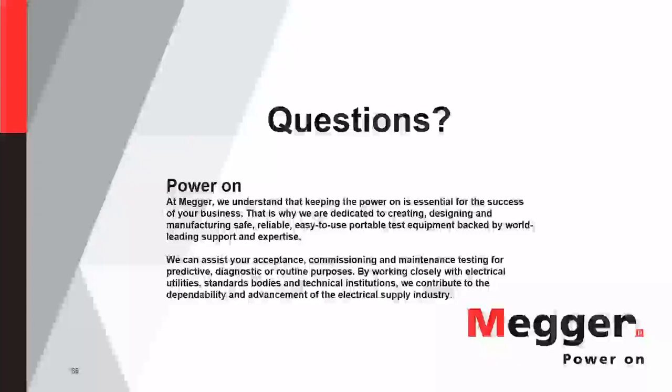The one place where I generally recommend a digital one for sure is on your rotary transducers. Because the problem when you use an analog rotary transducer is it's a resistor. You can't keep spinning this thing around. You actually don't have a full 360-degree movement. And so it goes from 0 to 357 degrees, and then it resets itself. So if you're not paying attention and you hook up this rotary transducer, and it's right at, say, 340 degrees, and it's going to spin and go through that 357 and reset, your motion's going to be bad.